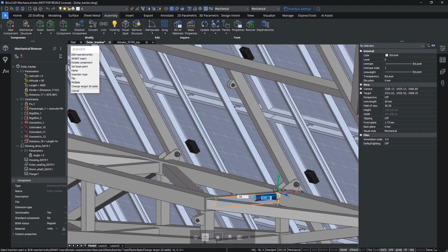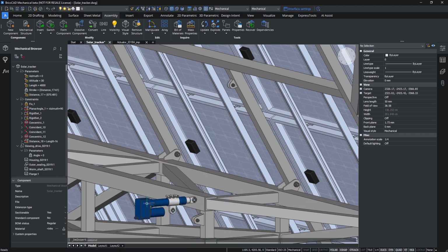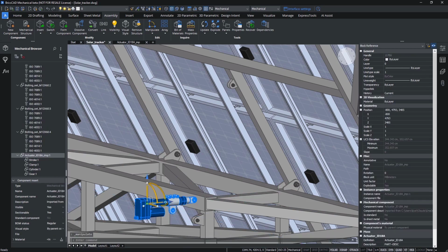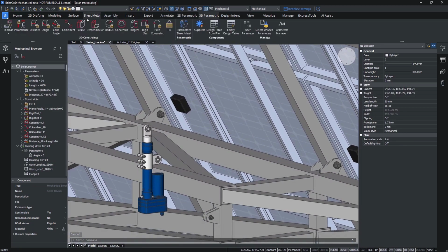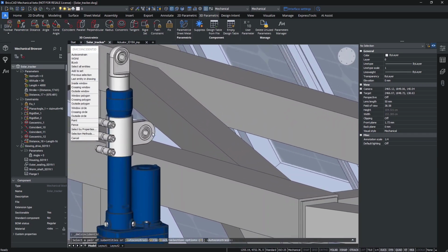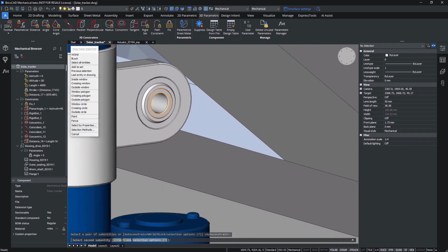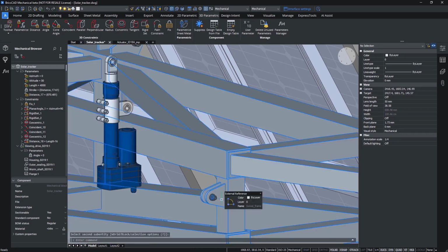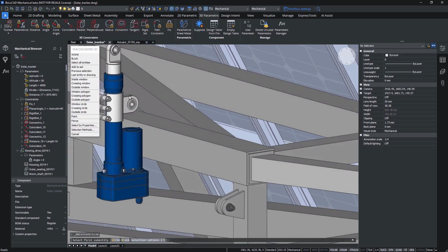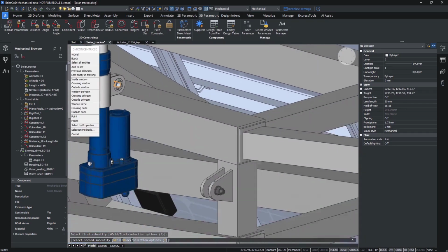After reviewing its correctness separately, we can then insert it to the main assembly and roughly place it in the 3D space. Let's tilt the frame and add a few necessary concentric constraints. We need one between the faces and one for the rotation axis. Note that those axes are always fully identifiable even though the 3D data is not native.